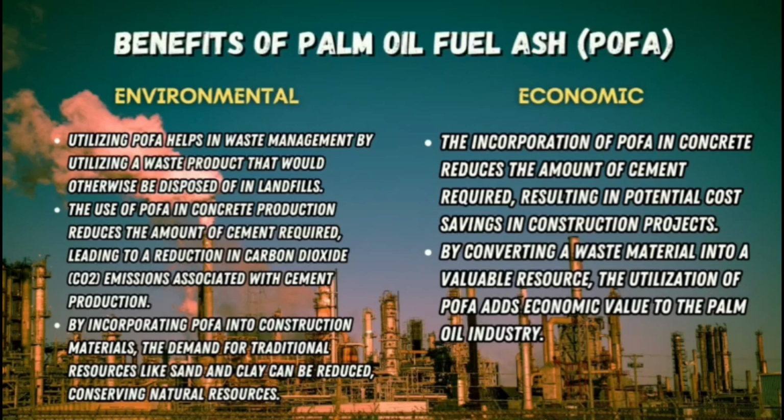Next, by incorporating POFA into construction material, the demand for traditional resources like sand and clay can be reduced, conserving the natural resources. Next, if we look from the economic side, when we use POFA in concrete, we can reduce the amount of cement required, resulting in potential cost saving in construction projects.